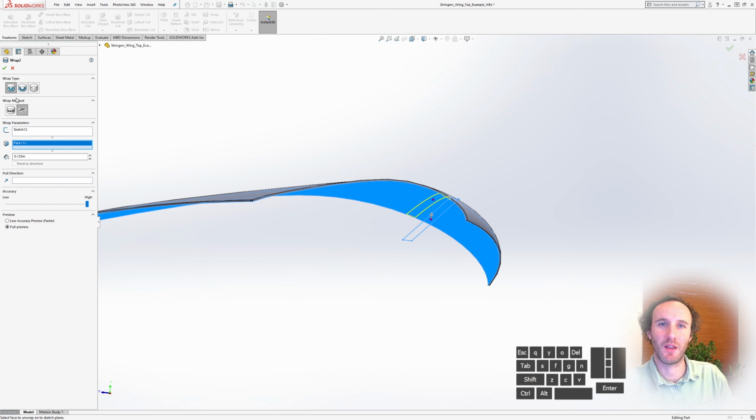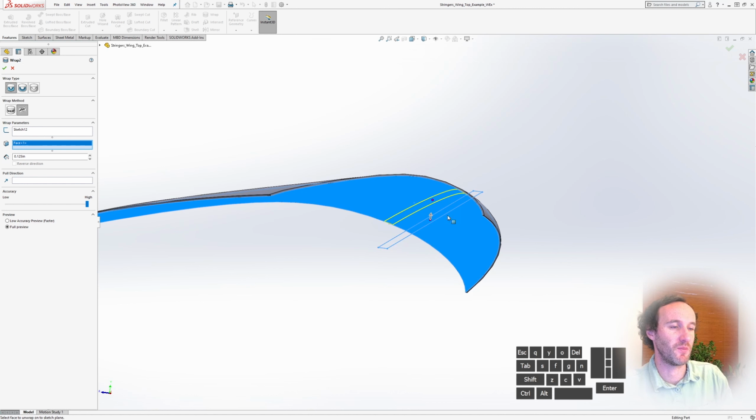Now this is an analytic method here. It's a spline surface. Sorry, it's not analytical, it's a numerical spline, because this option here will only work on certain shapes that have a closed form solution like a cylinder, whereas this is a general case of a spline surface that we're going to use.